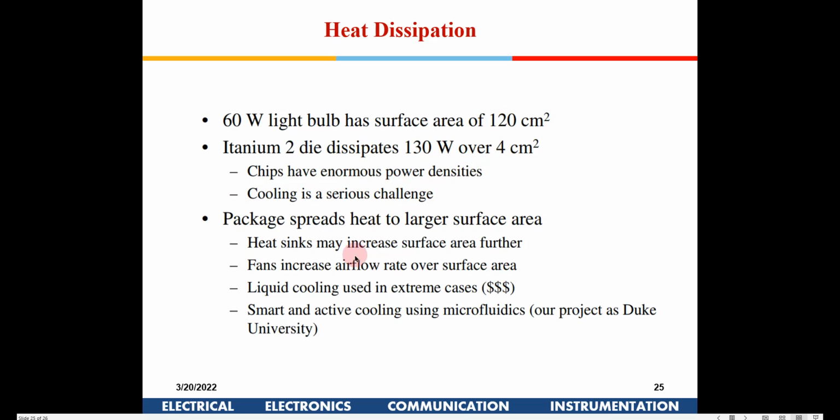So you will find these chips can get much hotter than your incandescent bulbs, right? Hence you will find that most modern day processors require a fan, and you also employ liquid cooling these days. Many high end processors use a water cooler itself. You have coolers which run water through small orifices, and that cools the IC. On top of that IC, you place a cooling system. So heat dissipation is a major issue these days, and you will have to take care of it.